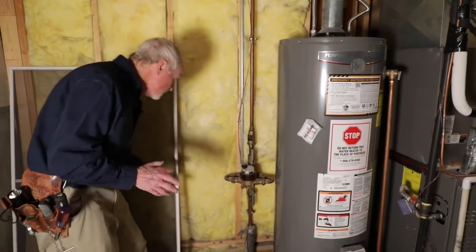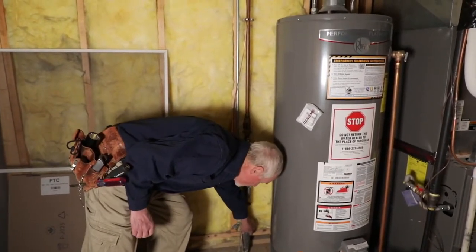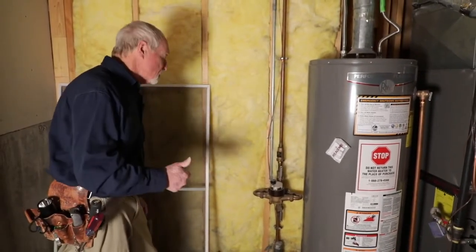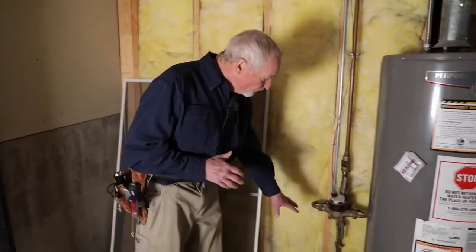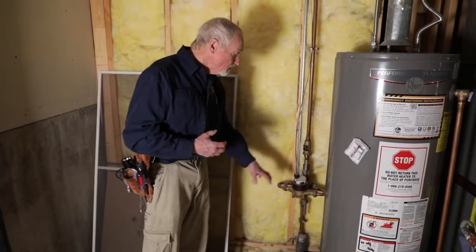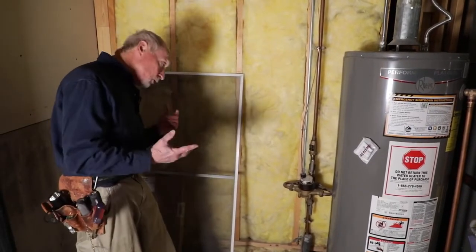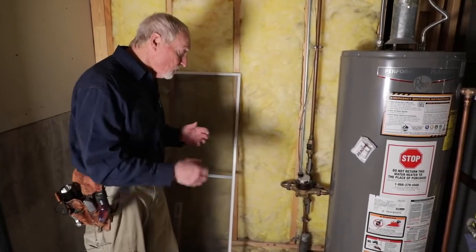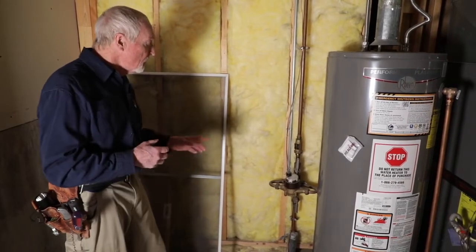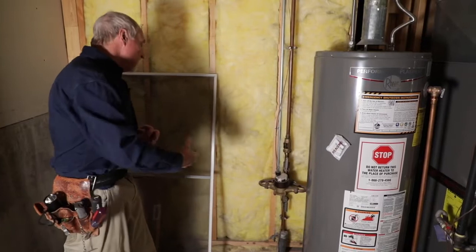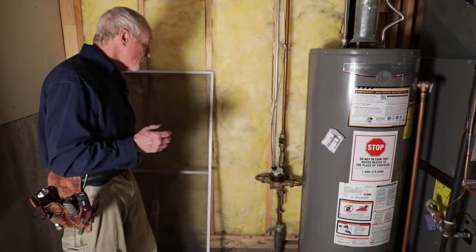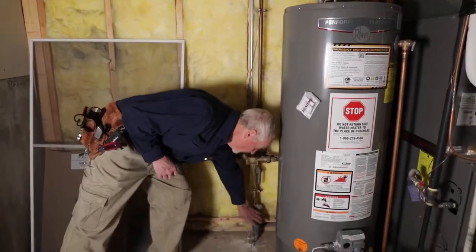A couple of things about this out of the gate. Somebody put a sleeve around the copper pipe coming through the slab, which is exactly what we want to see. Whether it's simple plastic, paper, something that isolates that copper pipe from contact with the concrete, for two reasons. If the concrete slab moves and it's holding onto the pipe, it can move that pipe with it, maybe break something. And the other thing is mineral salts in the concrete can react with the copper and damage the copper, weaken it, and cause a leak. So we want to see this sleeve here around it.